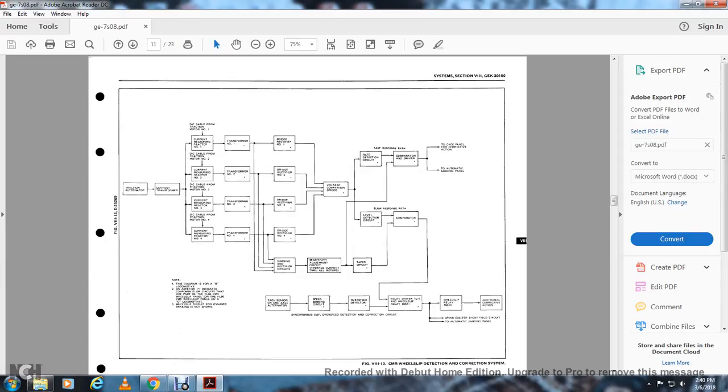Alright, we have figure 13-13 showing the traction alternator with the current transformer going into three different sections. From the top, current measuring reactor number 1 and 4, transformers number 1 and 4, rectifiers number 1 and 4, and then in the center you have the current measuring rectifiers number 2 and 3, transformers number 2 and 3, bridge rectifiers number 2 and 3. They also have these four transformers between the rectifiers go to a summing rectifier circuit with sensitivity adjustment circuit.